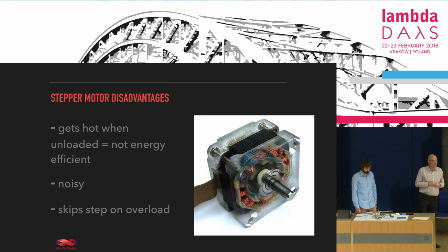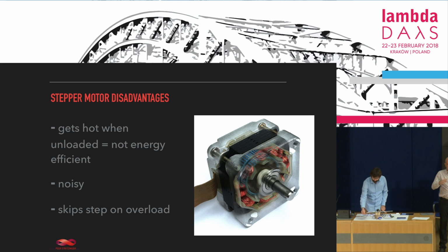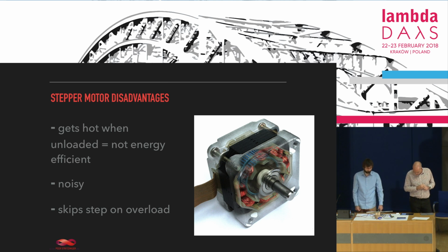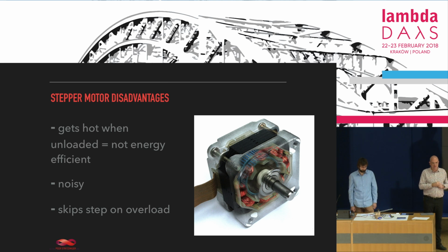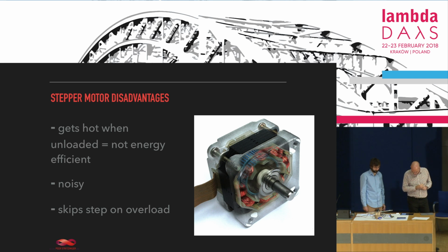And they also have pretty high torque, but they also have disadvantages. The disadvantage is that if you go step by step, basically, you dump the same energy for every step into the stepper motor. It behaves weirdly, because if it's unloaded, if it doesn't have anything to pull, then it actually gets pretty hot because it needs to get rid of the energy, which is also a waste of energy, of course. It's not energy efficient. They can be noisy because this stepping makes a piping noise, like those old printers. That's actually the stepper motor you hear.